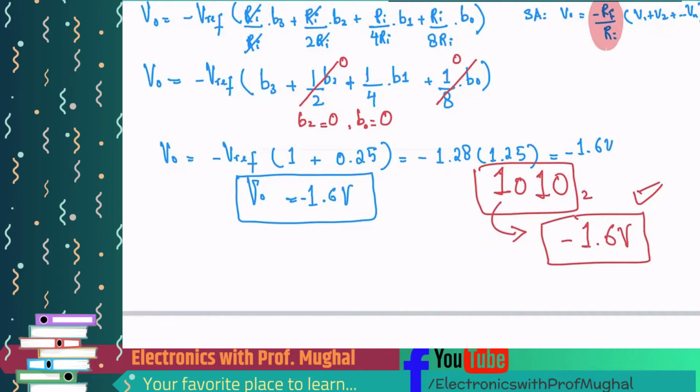So 8-bit is pretty standard, and 16-bit takes it to the next level. The more you break it down, my voice is basically broken into very small intervals, which are represented by some magnitude. In this case it's going to be a voltage, but it can also be a current. And this voltage represents a certain sound.